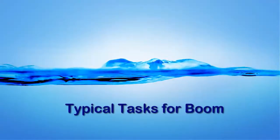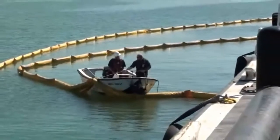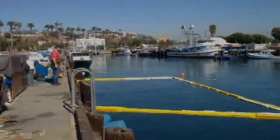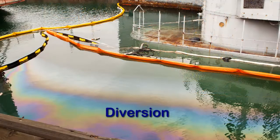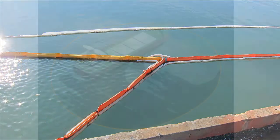Typical tasks for boom. Encirclement is the process of laying one or more barriers of boom around the source of the spill to keep it from spreading. Responders use encirclement near shores or on rivers where weak currents or little wave action make encirclement most effective. Diversion is the process of setting one or more lines of boom at angles into or across a moving slick's path to guide it toward an area where it can be confined and recovered.